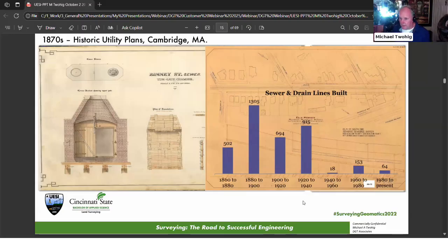So that Vassar Street, that is all reclaimed land. By 1900, that was a part of the marshland, and it got filled in over the years. And then the MIT campus was built on the other side, the south side of Vassar Street. But that was all reclaimed land. It was terrible soil. But even if the soil is bad, we still get decent results because when they cut through and backfill, a lot of times you may not see the exact utility, but you can definitely see, just like you saw on the street that we had up there, Western Ave, and looked at in the video, you can see those road scars in there.